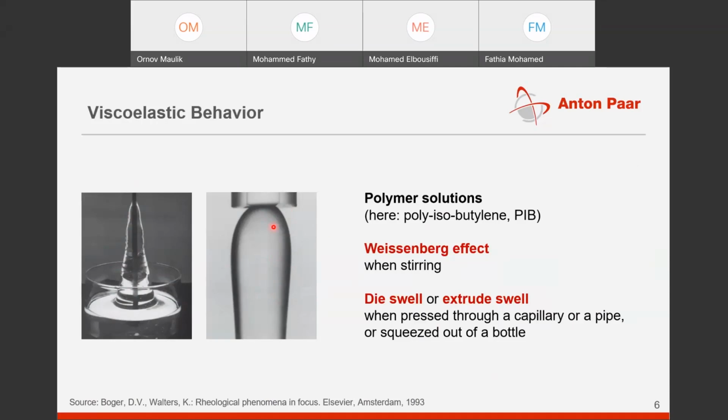molecular chains in the polymer do not get a sufficient amount of time to relax. When they do not relax, when they come out of that particular die, the molecules try to entangle and regain their structure. So you would have a swelling effect after it comes out of the die. This is an issue in most manufacturing processes of polymers, or in any application related to extruding.